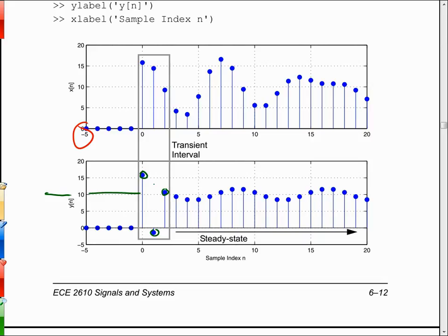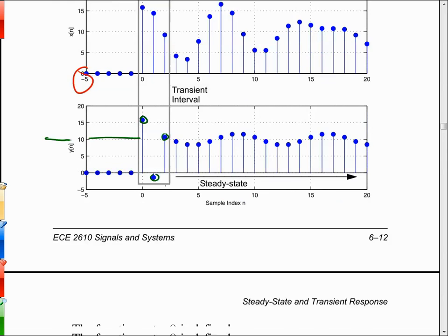You will relate to these things really well once you start playing with the test equipment in the lab, because the function generator has a knob on it called DC offset. You can look at the sinusoid coming out of it on the oscilloscope, and if you twist the offset knob, you'll see the waveform on the scope will ride up and down with the DC offset. For this class, we have to be content with plots in MATLAB, which are our believability factor. That's what the computer is generating, and that's what's really going on.